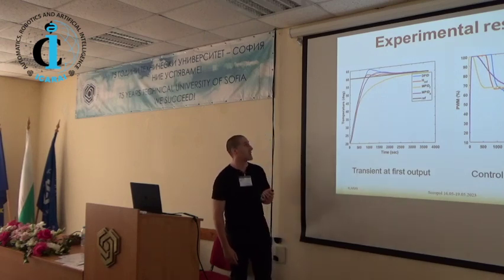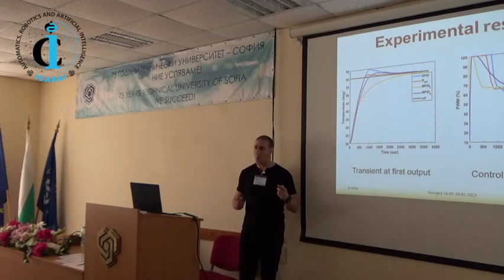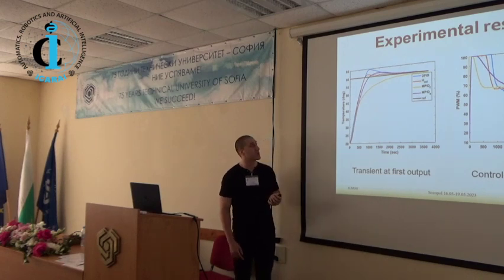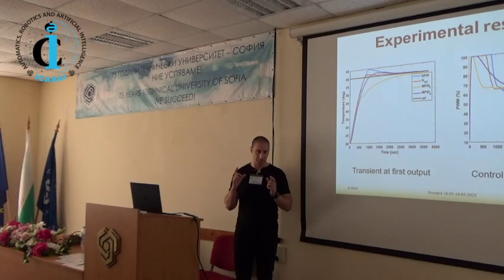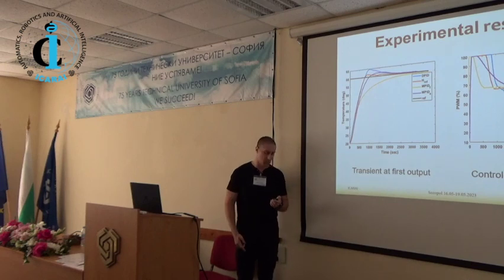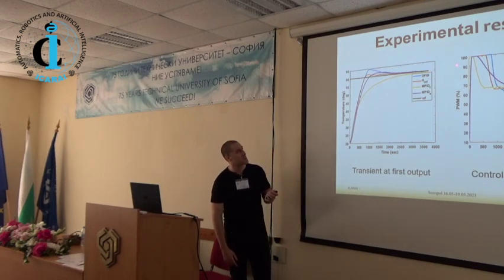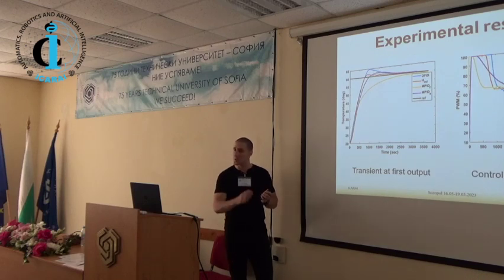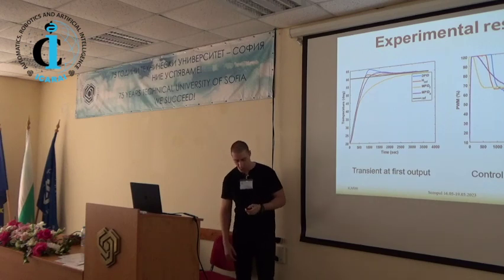The outlier here is the so-called fast PID controller, which, as I said, has a wider bandwidth, but when we hit the saturation limit, I'm not sure here if it is a numerical problem, if the used anti-windup mechanism is the problem or the parameters themselves, but what happens here is that for a short amount of time we exit the saturation limit, and despite the fact that we still have a big control error, the control signal decreases, which leads to this slow dynamics and slow transient response.